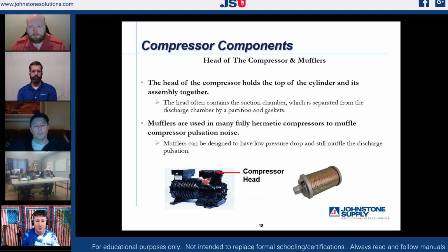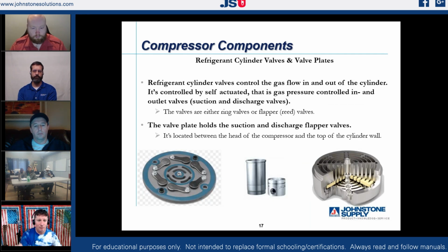So if we are on that valve plate, here's my valve plate on the left-hand side. Let me grab that Sharpie. If we look at those valves, here are your actual valves, right? We have holes underneath of those that our vapors come through as we're pumping. Think about how many times those valves are opening and closing. On every rotation, they're opening and closing, opening, closing, opening, and closing.